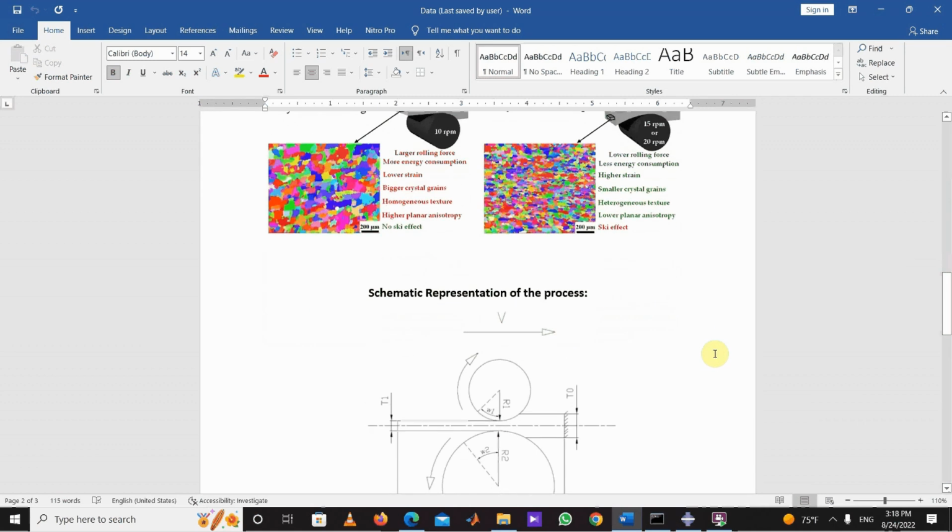Okay, after this brief introduction, we are going to simulate the deformation of an aluminum plate under asymmetric rolling process. By this simulation, we want to monitor and visualize the deformation behavior of the workpiece, besides the process forces which are exerted on the rolls during the process. In addition to that, the amount of normal and shear strains and stresses which are induced on the workpiece during the forming with the ASR process are the parameters that we want to monitor.